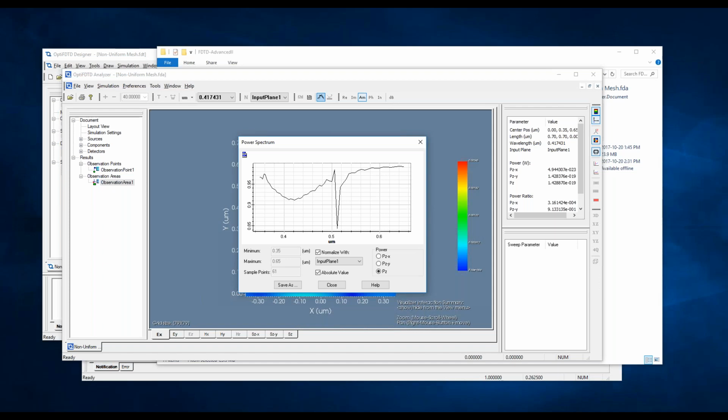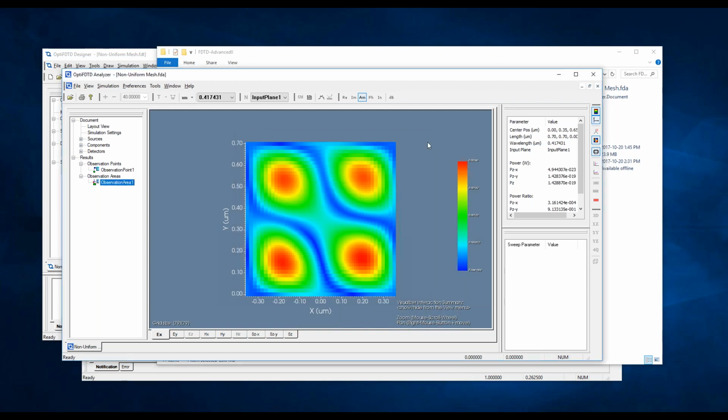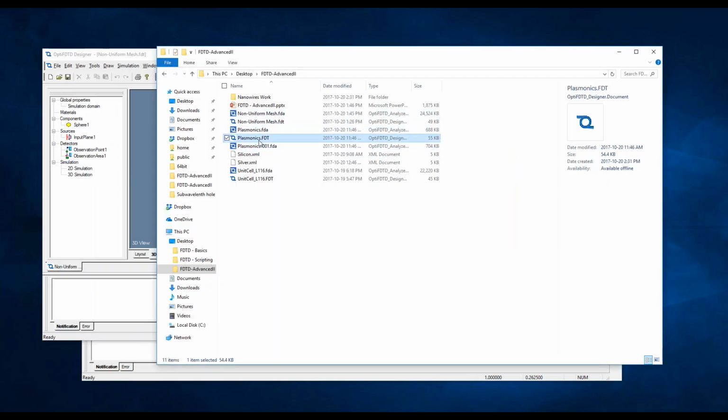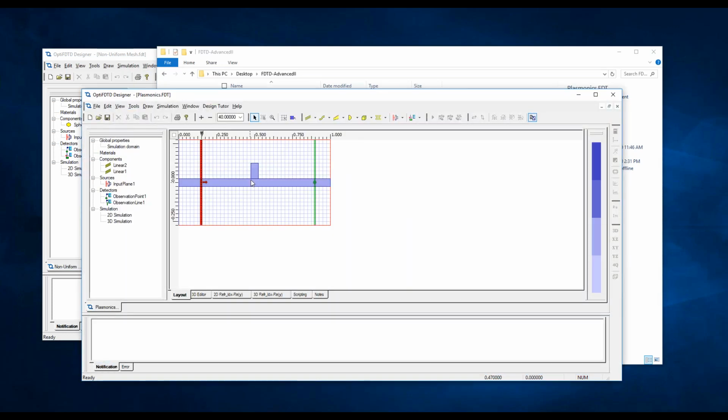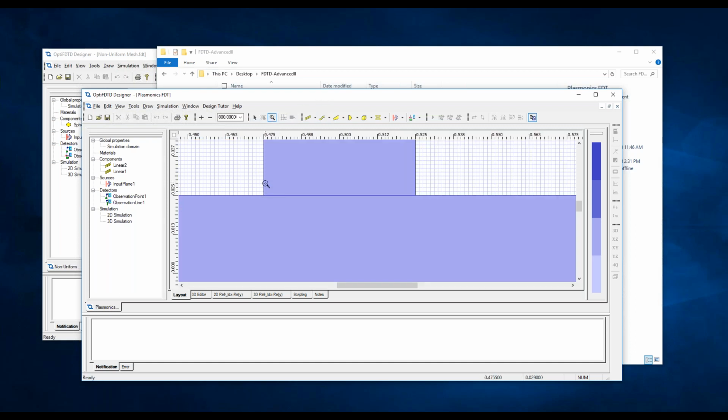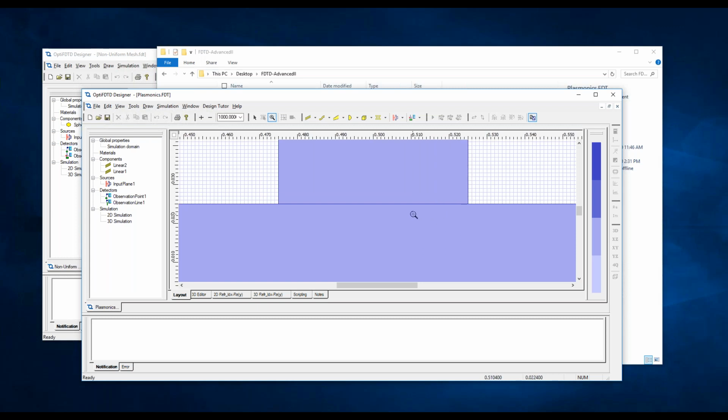Thanks, Brian. The first question we got is in regards to the plasmonics example we did, which is this one here. What I did was I sat this tooth up on top of the waveguide, and I chose my sizes so that in the layout, these are the same. This one was centered, with a width of 0.05, centered at 0, which means this edge was at 0.025. I specified I wanted this one to be located at 0.025.